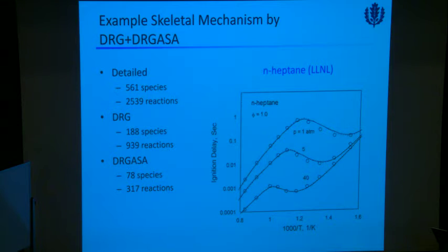So we use our cluster with 1,000 core to do reduction. It still takes 2 weeks. So because we need to test everything. So several thousand reaction states. So basically hundreds of autoignition cases, hundreds of PSR cases, and also sometimes you need to validate the 1D flame speed, the S-curve for 1D flame extinction, sometimes 1D non-premix flame extinction, 1D premix flame extinction.